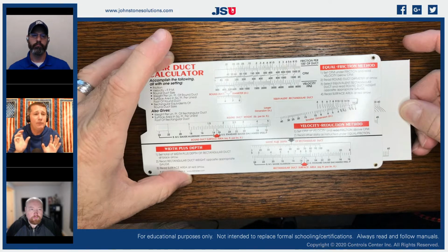All right, so if we want to find out how much airflow can be run through a duct, we're typically looking at that based on static pressure, right? And we all know that manufacturers of HVAC equipment, unitary equipment in general, design their blower motors around 0.5 inches of static as being ideal. Whether that is a permanent split capacitor, an ECM constant torque, or an ECM variable speed, they design those for around 1/2 inch of static.